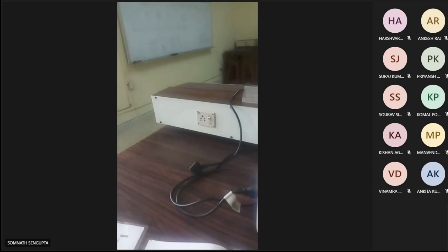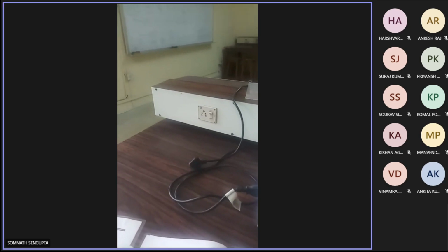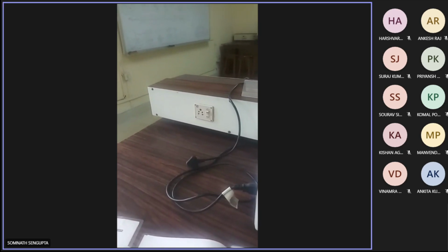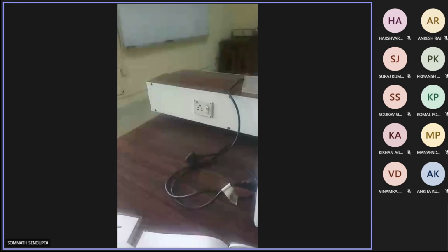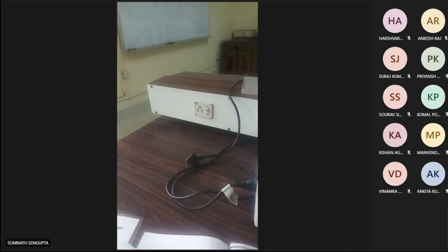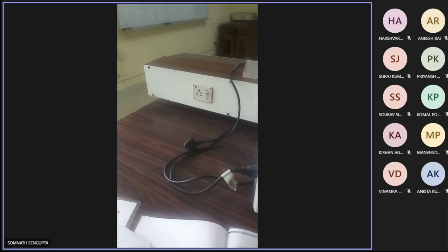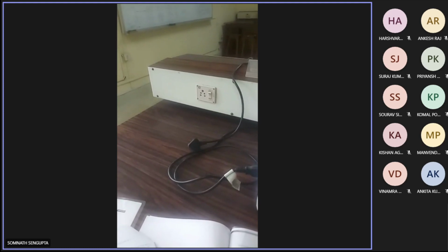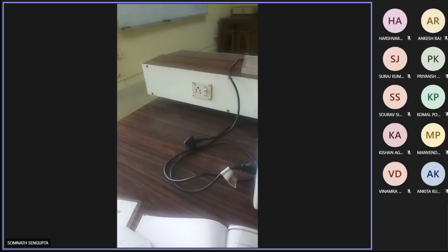Okay, and that duration will be selected such that it matches the clock signal that you have used at the transmitter. That way you can generate the clock signal, and it will act as a clock recovery circuit. That is the important thing.